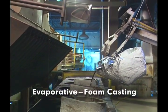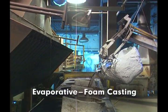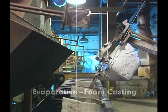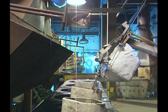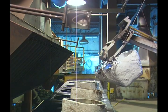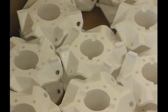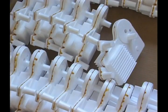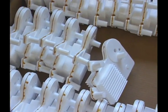Evaporative foam casting refers to the use of expendable polystyrene foam patterns in molds made of dry, unbonded sand. The process is also known as the lost foam or expanded polystyrene process. The pattern may be a single piece, or for complex shapes, an assembly of molded pieces.